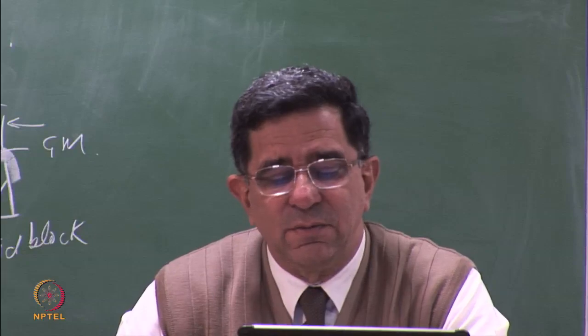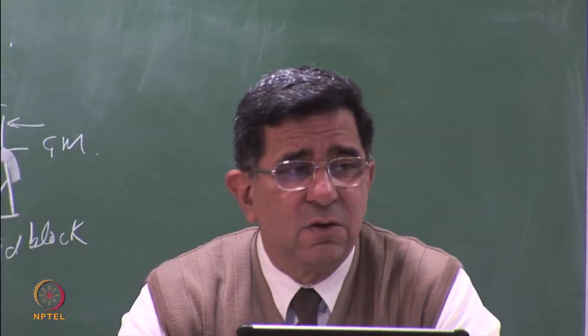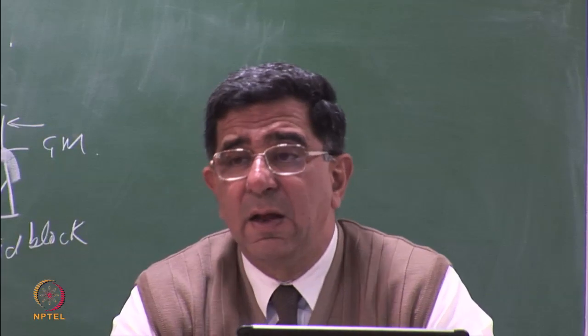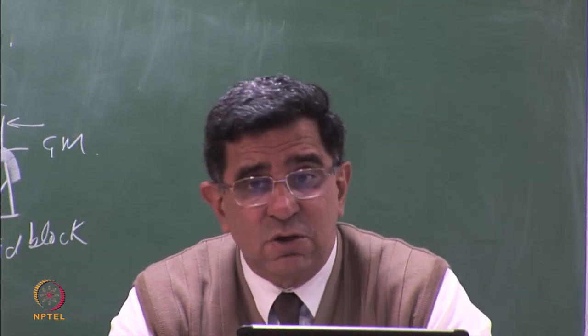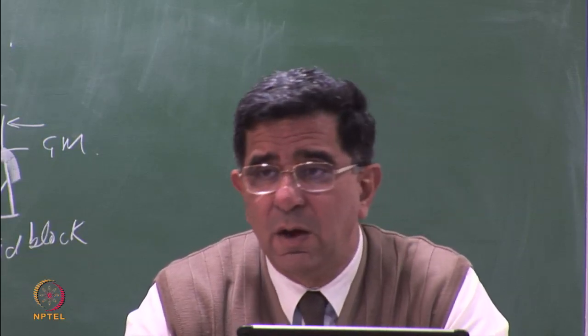And see the value, extremely low. You do get a cohesion intercept sometimes in your direct shear tests, and the cohesion, this should be called adhesion. Cohesion is soil to soil, this is adhesion intercept. So the adhesion intercept in unsaturated soils is higher, in saturated soils is lower.